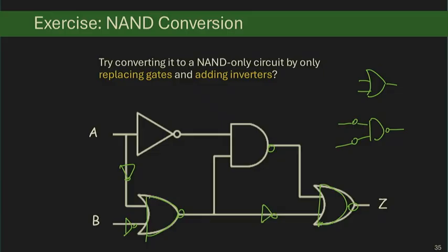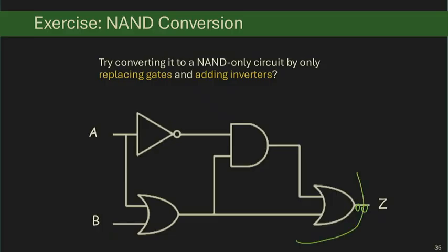So where did you start? Did you start from the OR gate on the left? You start on the right. So start on the Z output, and then introduce 2 inverters over here, and then propagate one of them backwards to become an AND gate with inverted inputs. Right? That's how we put the inverter over here, and then add another inverter at the bottom.